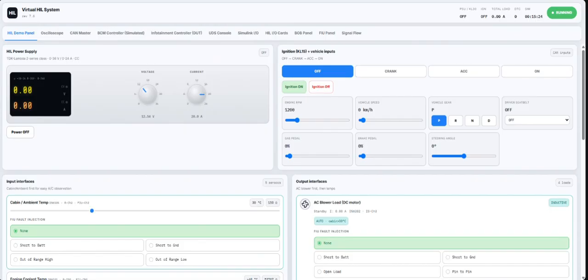So those scenarios we will be able to prepare, and while creating the scenarios, we'll understand what parameters are required. Like for example, how exactly the time to collision is calculated, so which particular point we should consider to calculate the TTC. Those kinds of concepts we'll be discussing while creating the scenarios.